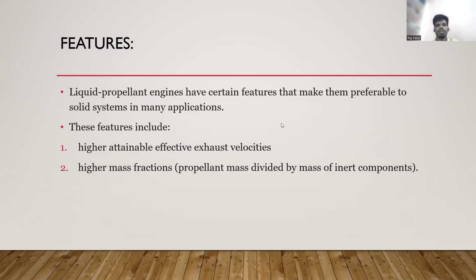Liquid propellant engines have certain features that make them preferable to solid in many applications. Here we are comparing with the solid propellant. Generally the features include high attainable effective exhaust velocities. In the liquid propellant, attainable effective velocities are higher compared with solid propellant engines, so generally there will be higher exhaust velocities in liquid propellant engines.